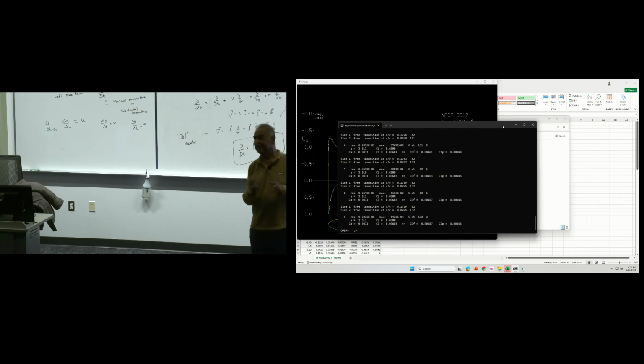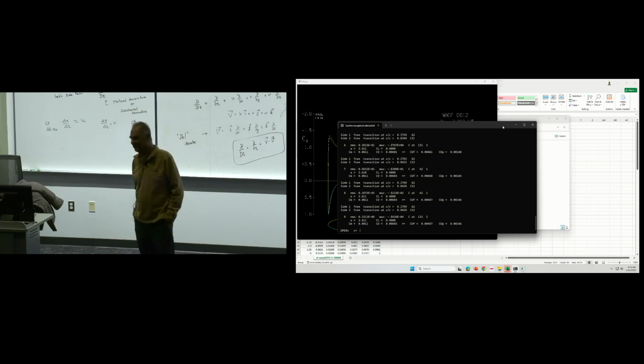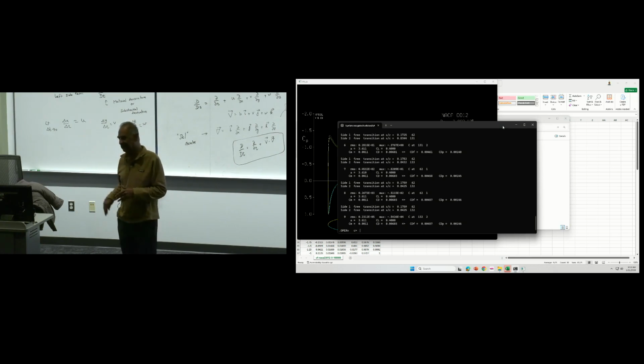Okay. Any other problems you have had in XFOIL? We only have 5 minutes, so I'm going to just ask questions, then we will stop. Yes, please. Just a small question. It wasn't happening with NACA 0012. It was happening with NACA 64A012. Okay. I didn't do PCOP or PANE, but see if it helps. Yeah, I changed the iterations to 300. It was not converging at 250 even. So yeah, sometimes it'll take a large number of iterations.